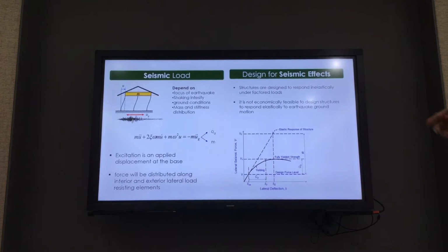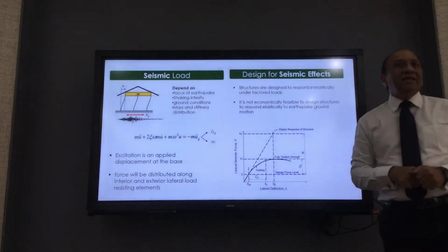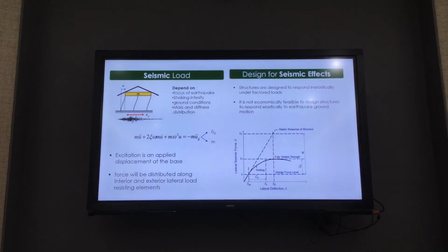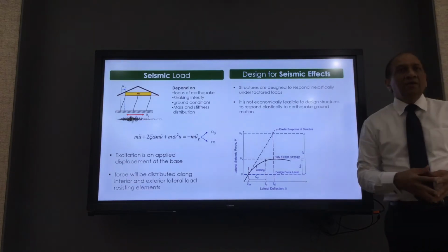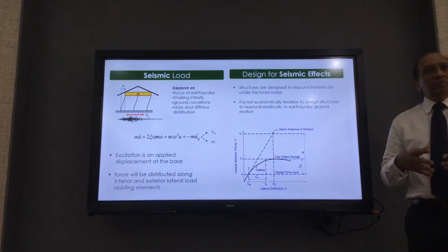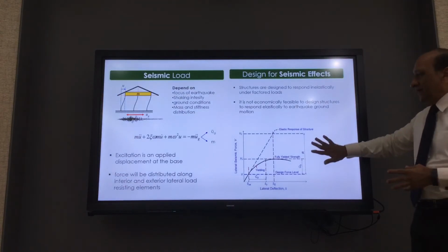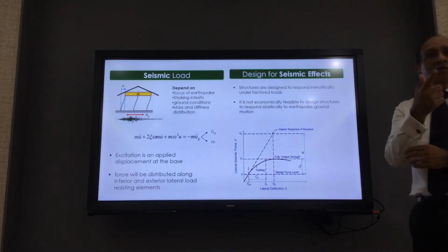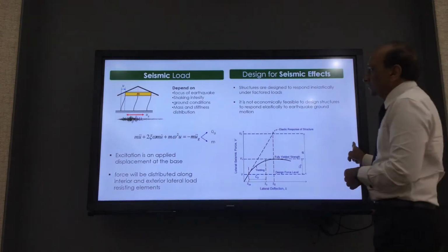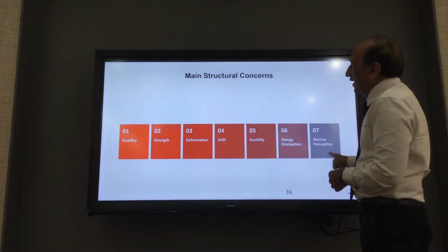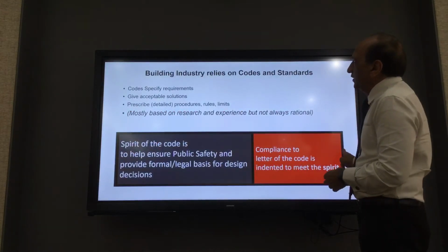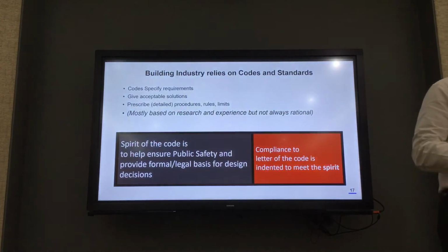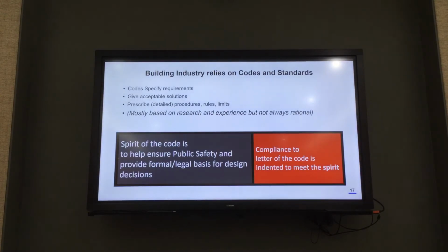But the problem is that they are often very wrong and they cannot be estimated reliably for various systems, and most of the time they are too large. So especially for tall buildings, this R factor tends to be quite wrong. I think you have seen this presentation many times. You were there with the Ron Clemency presentation also. So he also mentioned that. So this issue with the R factor is one of the reasons that we try to do more than the code. We are not saying that the codes are bad, just that they are not applicable in all cases.